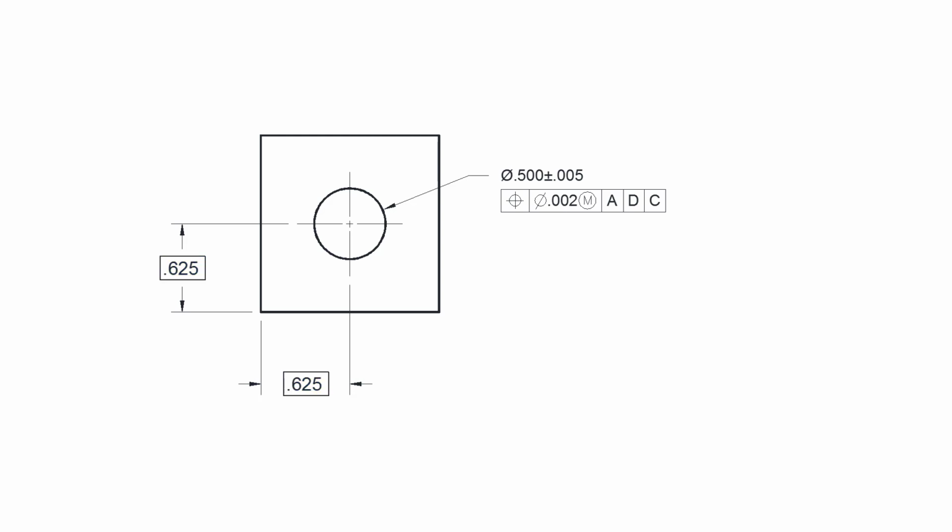Similar to what we have previously discussed with angularity tolerances, basic dimensions must be used because the tolerance zone is defined by the geometric tolerance found in the feature control frame, not the dimension tolerances. Let's begin by taking a look at the shortcomings of conventional tolerancing when locating the center of a round feature of size. Here we have a drawing of a simple block with a hole in the center of the object